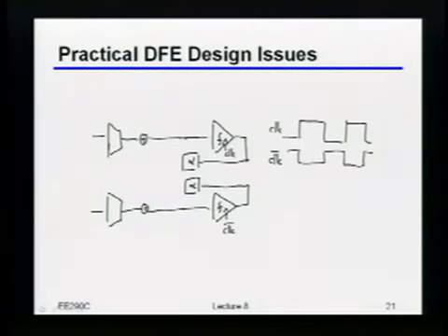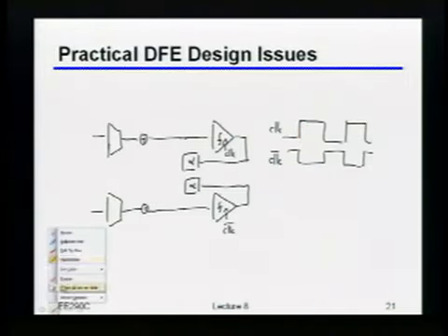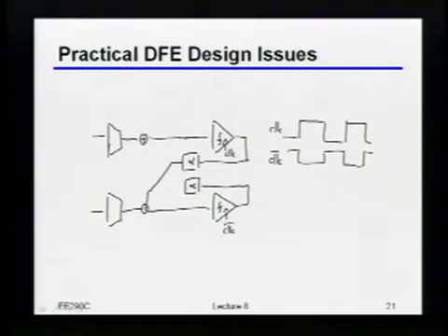then a lot like we talked about previously with the interleaved designs, if I need to cancel the previous bit from the thing that just made a decision, or rather, when I make a decision here, once clock bar goes high, the thing coming from clock is going to be the previous bit, right? So in other words, in order to close that loop, what you have to do is something that looks like that. Right, so in other words, the decision that came from the even or the positive clock edge gets fed back to the negative side. And the decision that came from the negative clock edge gets fed back to the positive side. And just to make sure there's no confusion, these are, of course, in principle, or at least in practice, tied to the same input voltage. Okay?